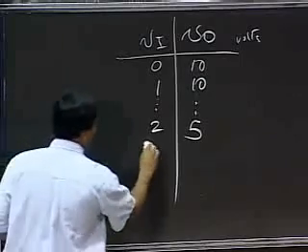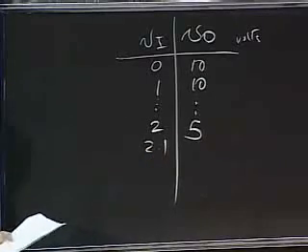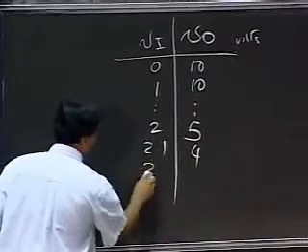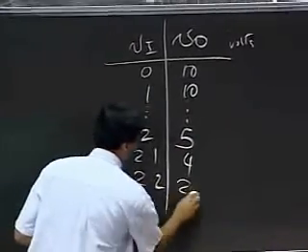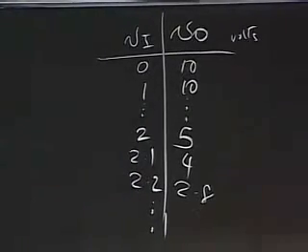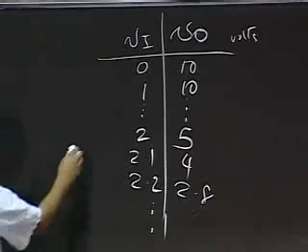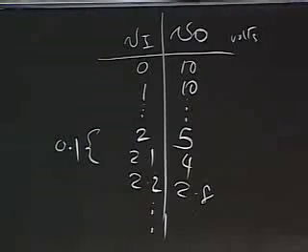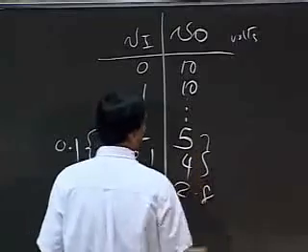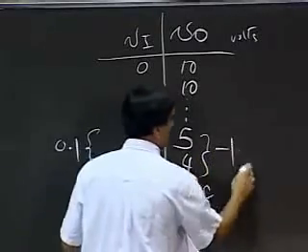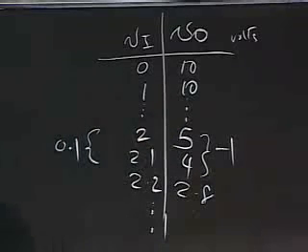And then you can go and do the math. If it's 2.1, I get 4 volts here. 2.2, I get 2.8, and so on. Notice that the 0.1 volt change here, when I go up a 0.1 change this way, results in a minus 1 volt change there.